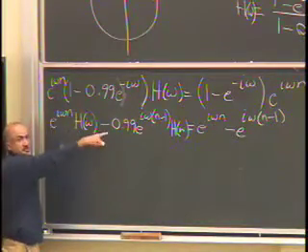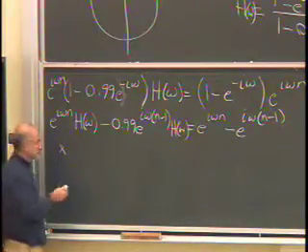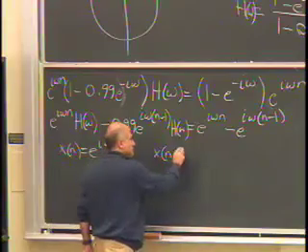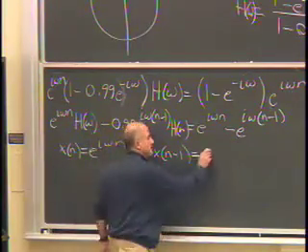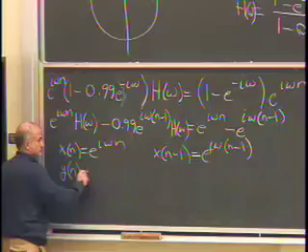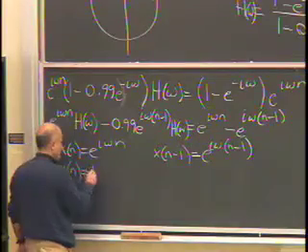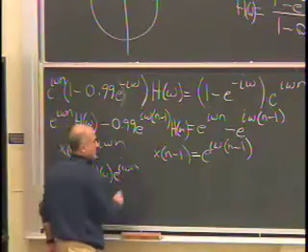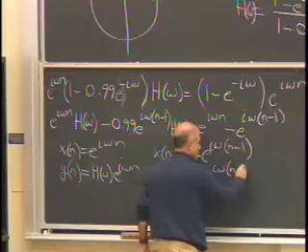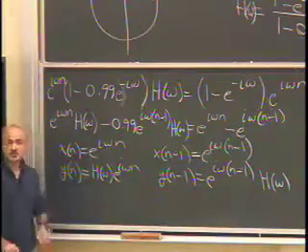And remember, I'm trying to get back to the difference equation. When we went the other way around, from the difference equation to the frequency response, we plugged in x of n equals e to the i omega n. So x of n minus 1 was what? E to the i omega (n minus 1). And the corresponding output was what? This goes in, what comes out? H of omega times the same complex exponential. So y of n minus 1 will be this complex exponential times H of omega. And now you recognize all of those terms in this equation. That's how you make the connection.